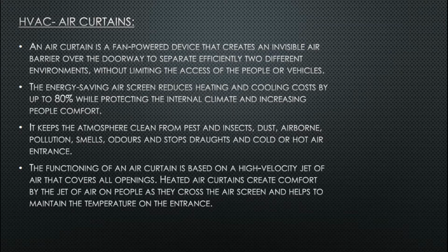The energy saving air screen reduces heating and cooling cost up to 80% because it acts as a seal and stops the leakage of heat or cold air going outside from the conditioned environment. It keeps the atmosphere clean because it stops the dust and debris from the outside environment from entering the clean environment. The functioning of an air curtain is based on a high velocity jet of air that covers all openings. Heated air curtains create comfort by the jet of air on people as they cross the air screen and help to maintain the temperature at the entrance.